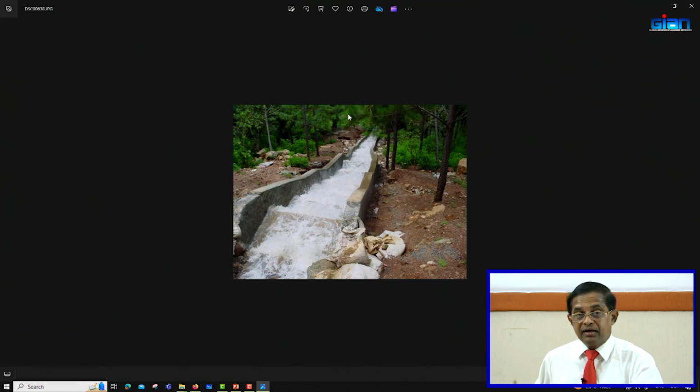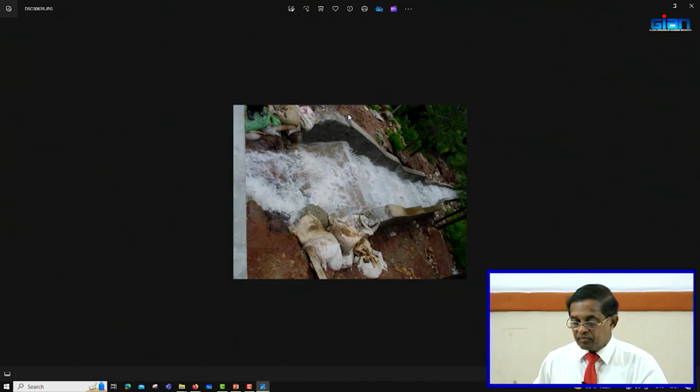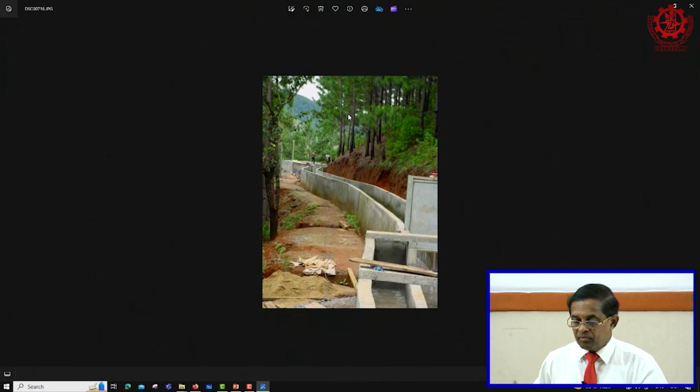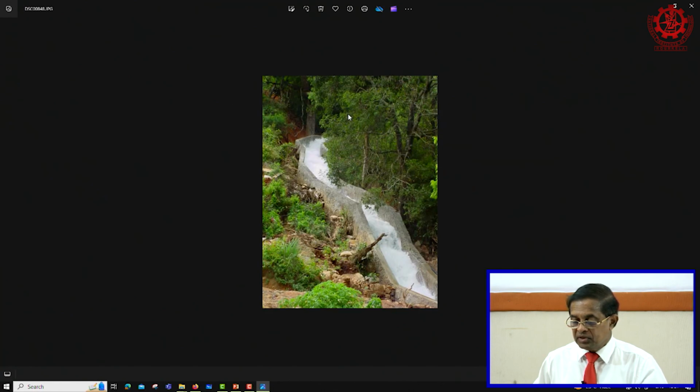Here you can see, when the breaker trips, gradually water will be allowed to overflow, not instantaneously. The deflector will first work, but then you will gradually let the water overflow at the forebay tank. See the overflow happening in the overflow canal. So, if somebody is sitting here, it is dangerous when the water comes.